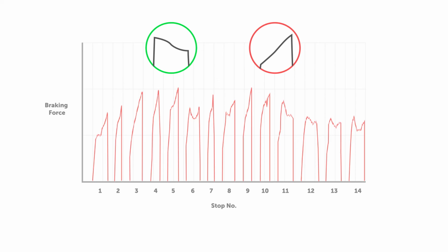This does depend on the aerodynamic downforce of the vehicle though, with vehicles producing higher aero loads being able to make use of pads with higher initial bite, as all other things being equal, they will have more grip at the maximum speed when the brakes are applied. Naturally, pads with higher initial bite will increase the chances of the brake locking, but this will be more of an issue for vehicles producing less aero downforce.